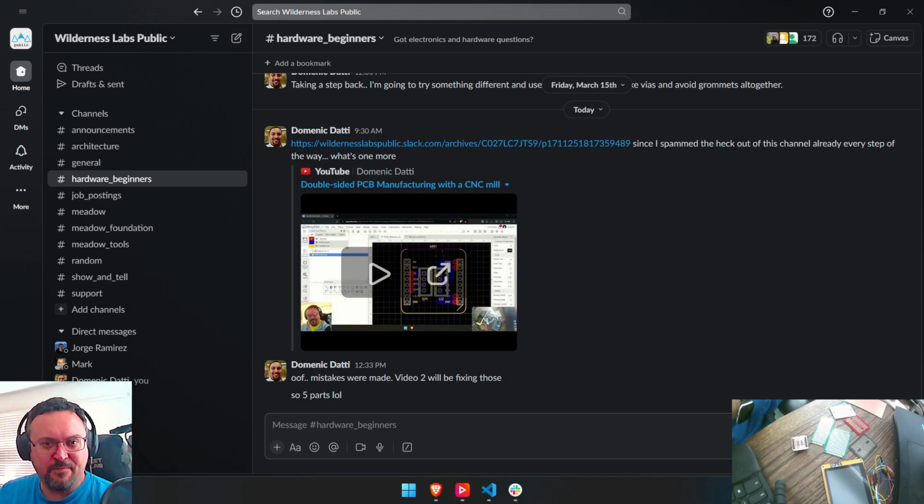I like that they have basically 0.5 millimeter separation between them, and I don't want to have to change the whole design to make the traces just a little bit smaller, and then that cascades out to the entire design. Now all the traces are smaller, instead of just, I can go and change it in FlatCAM.